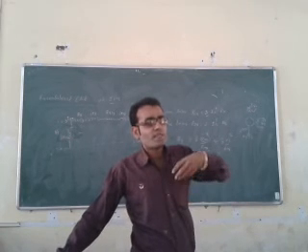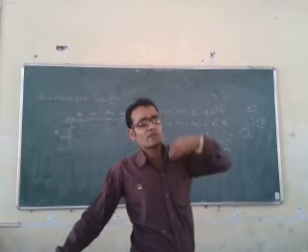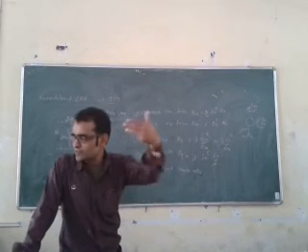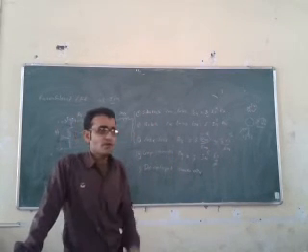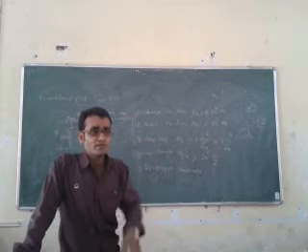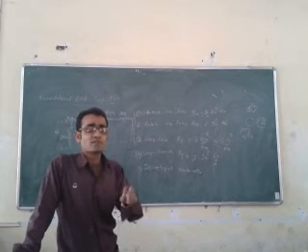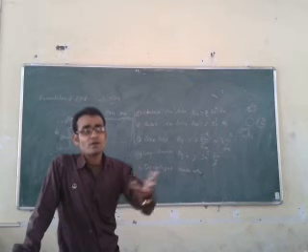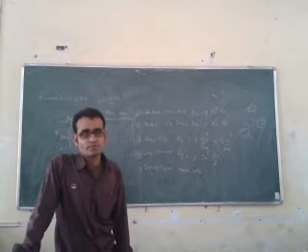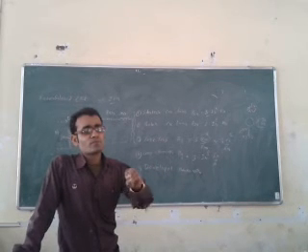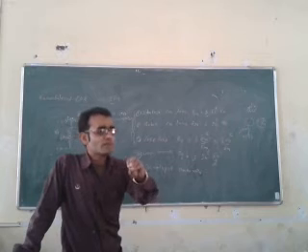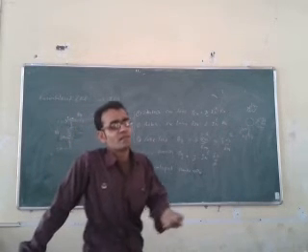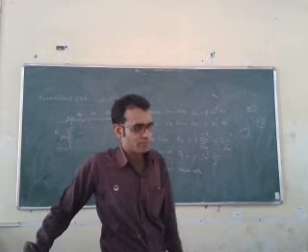Then we observe how much power is transferred to the rotor, which is gap power. Once the power is transferred into the rotor, again we have to calculate some of the losses of the rotor. And then we found that there is a generation of torque inside the rotor. That torque is responsible to produce power inside the rotor or on the shaft. That power is the developed power inside the rotor.